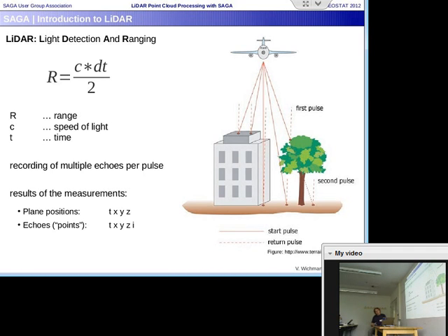And you get not only 2D information, but you get real 3D information. So we can have points that are exactly located at the same XY coordinate but have different Z coordinates. This is something special to this data too, because in case you would like to convert it to a raster data set, you have to decide which point to use for your elevation value. Do you like to have something like a ground value, or something like the top of the tree? You must decide, because in a raster you can only have one elevation. It's not really 3D, it's 2.5D.